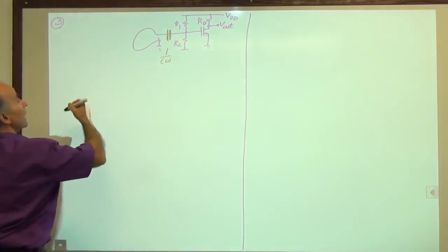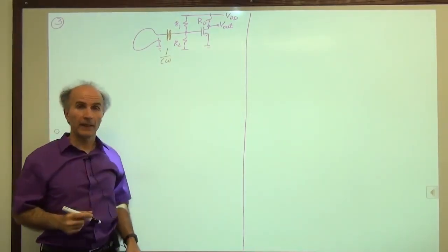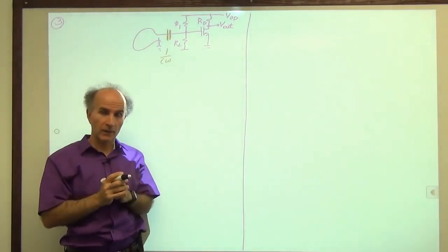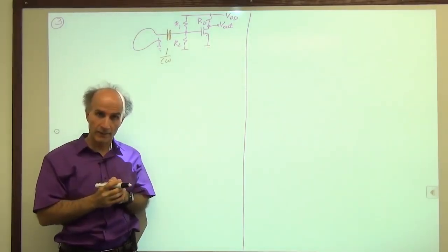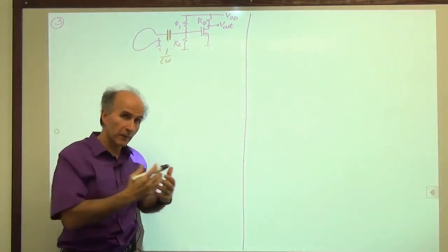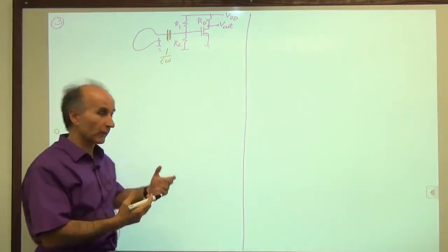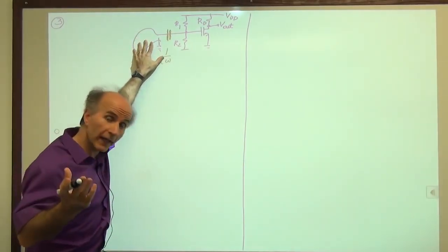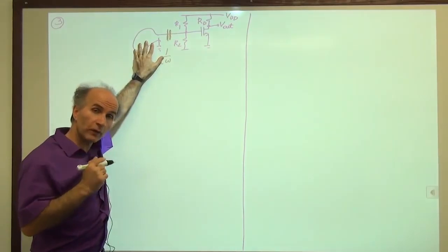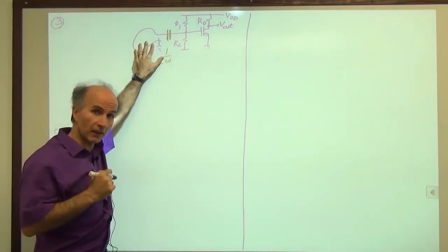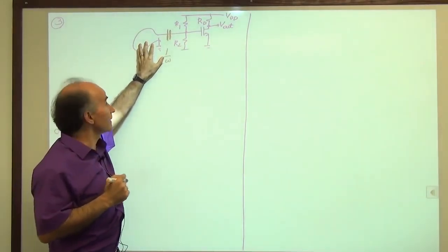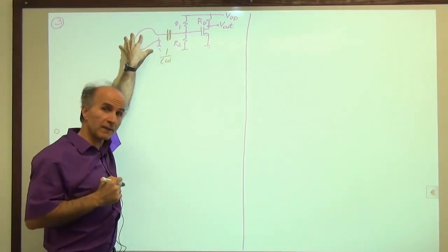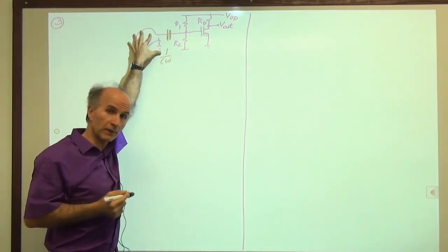All right, so what this tells us is the following. Anytime we have an amplifier, or any circuit for that matter, that has some bias conditions, and we want to drive it with something, an antenna, or a microphone, or another amplifier, we have to worry about disagreement between the bias that this guy needs here and the condition that the preceding stage or the preceding device produces.